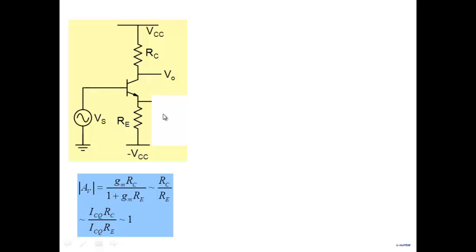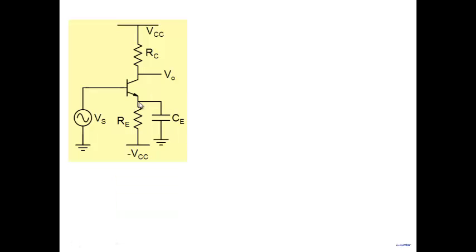So in that context, what do I do then? If I remove the capacitor, the gain is going to 1. So obviously I need to connect something at this particular point. Because remember, what are we trying to do? We are saying we need RE for biasing, and we need substantial RE for biasing properly. But under AC or small signal analysis, if you go back, we need this point to be ground. AC ground or small signal ground.